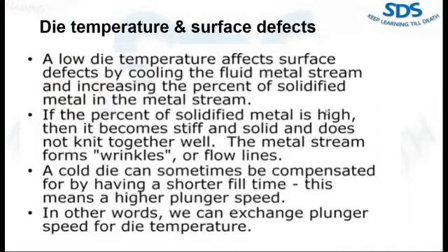So if we decrease or we are not able to maintain the die temperature, right? Minimum die temperature, yes, we will talk about this: what is the minimum die temperature, or what is the maximum, or the die temperature range? But if we are not able to maintain this minimum die temperature range, we'll increase the percentage of solid, right? So as we increase the percentage of solid, we are going to increase the filling time, right?